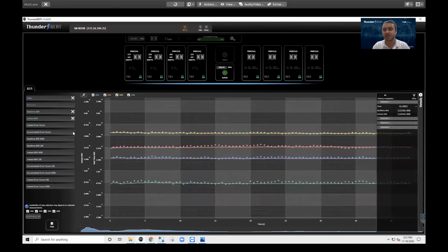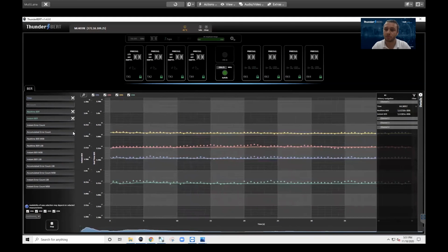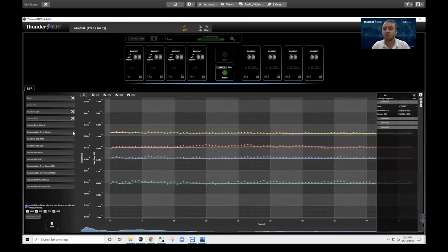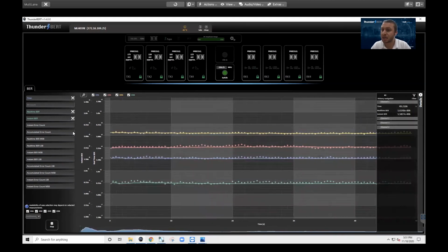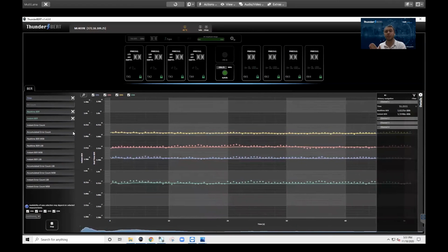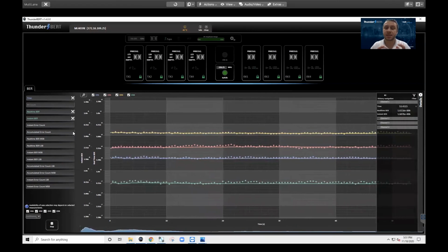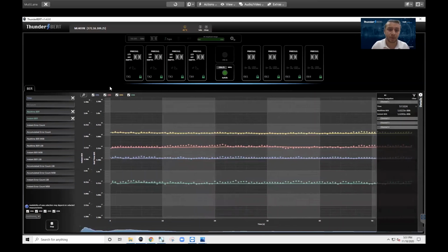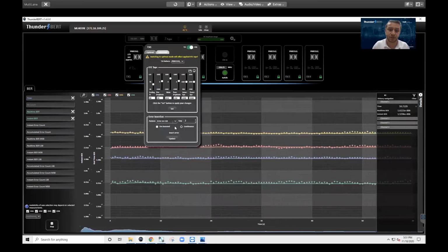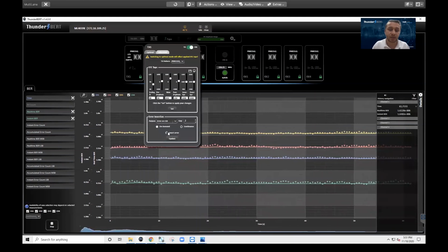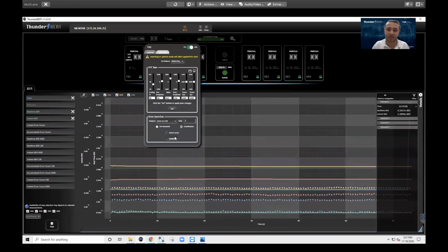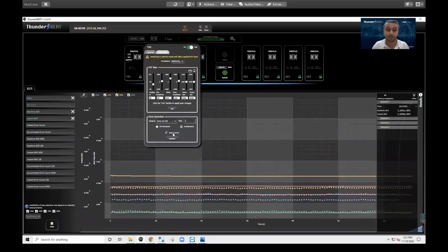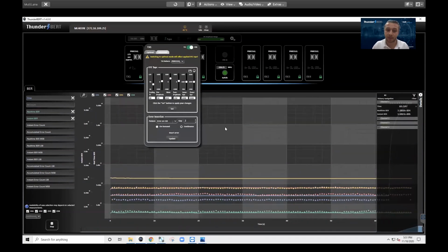So whatever I show on the graph is completely independent from the fact that I'm tracking all the measurements at once. So let's say you started this test in your own lab, and you see 4 channels running at 1E-6. That's what you expect. Let's say you get pulled into a meeting. Let's talk about error bursts for a second. Let's actually implement an error burst with our error insertion feature. So I'm going to insert a bunch of errors on the LSB side of the output pattern, just for a couple of seconds.